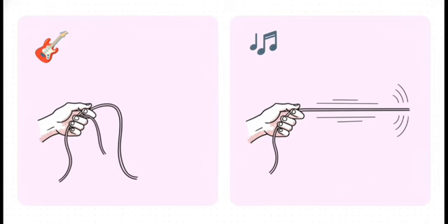And I think this guitar string analogy is just perfect for this. Without any prep work, a transistor is just like a loose, floppy guitar string. If you try to pluck it, you get nothing, right? It's just dead. But by applying what we call a DC bias, we're basically tightening that string. We're putting it under tension. Now, when our little AC signal comes along and plucks that string, it can actually vibrate cleanly around that new center point. And that's where we get our beautiful, clean amplification.